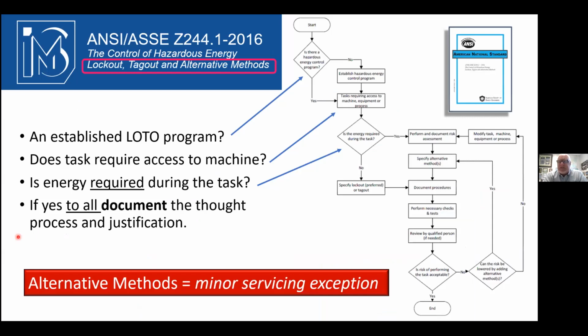When we turn to the standards, because that paragraph and even the guidance from OSHA isn't all that detailed, there is some detailed guidance out of the consensus lockout, tagout, or control of hazardous energy specification, ANSI Z244.1. If you don't have that one, this is the one you probably should have in your library.